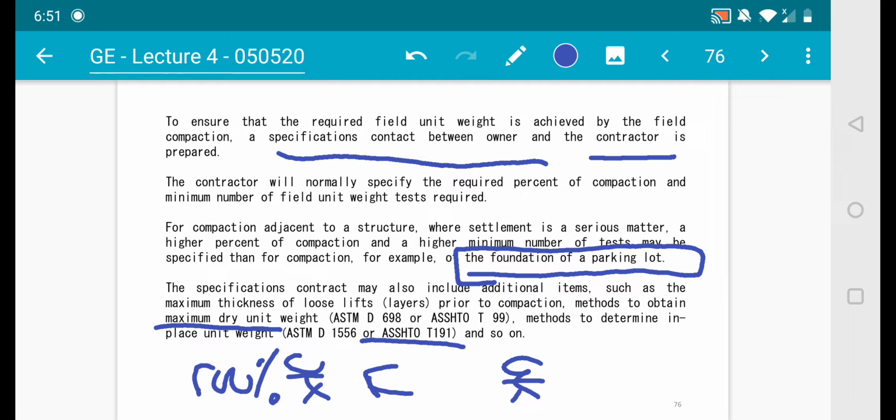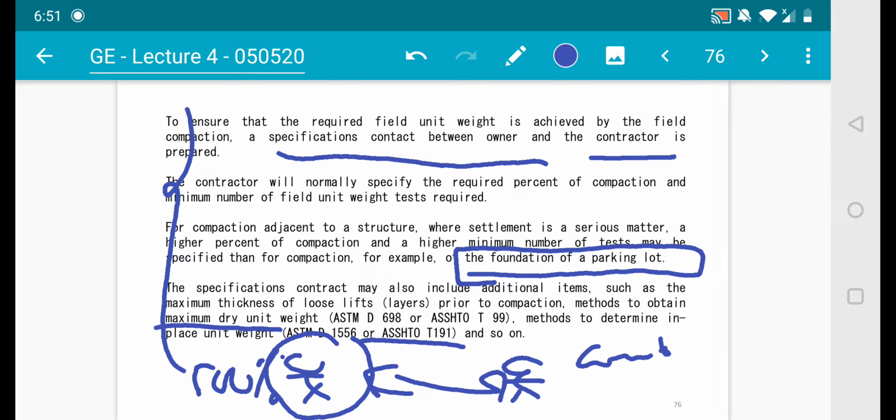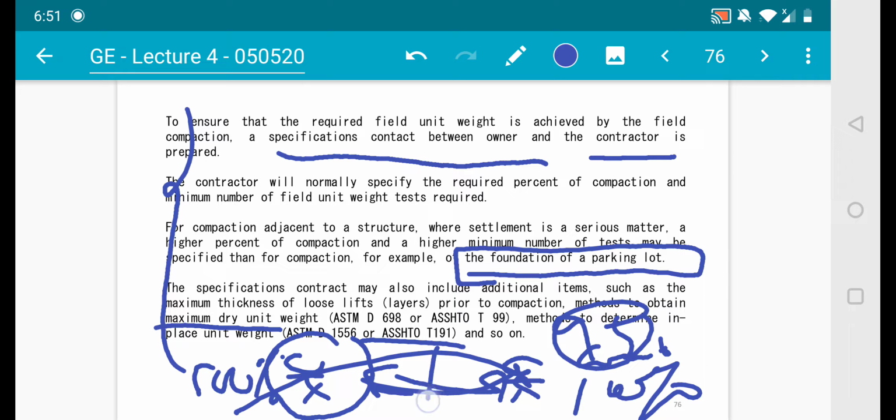So you as a client or as the owner need to be well versed with the characteristics or detailed properties of compaction tests so that you can channel the information to the contractor so he will do it accordingly. If you want 100%, the contractor must do 100%. If it's less, let's say 95, do it again until you reach 100%. So bind it in a contract.